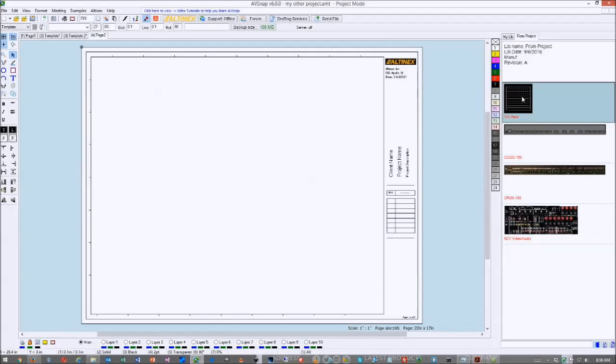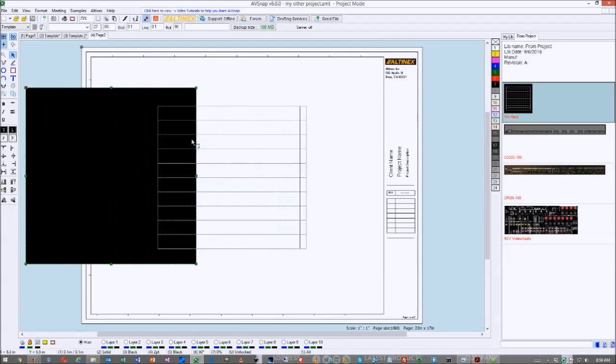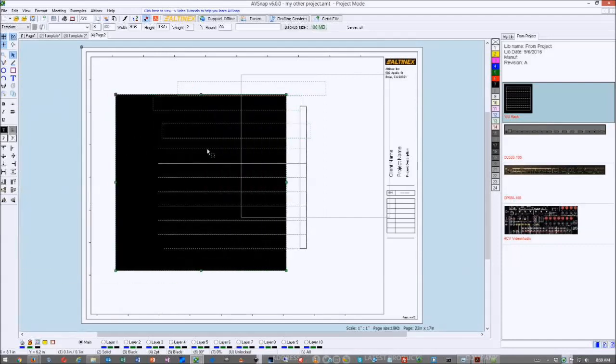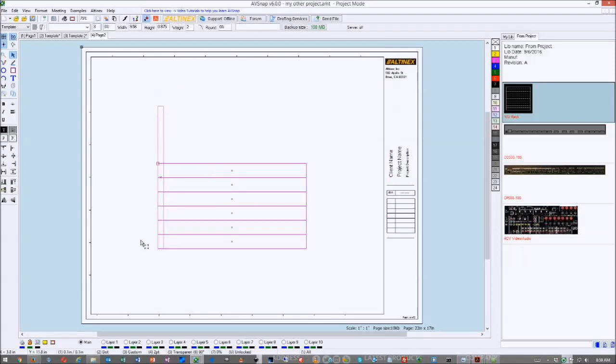And anytime we're going to bring the symbol on the page, you can see that it's broken in pieces. It's not an individual symbol. It's all different pieces together. So this is an important function in some cases where you want to just bring things in. For example, what I've seen a lot of times people do, they create different symbols for tags for the cables, and they may have different colors, maybe 5, 6 different colors. And when they bring it on the page, they just want it to be separate. So when they bring the page, they put the color chart in the corner, but it's not a symbol anymore because you can move the individual pieces around. So that's one of the functions that people can use also.